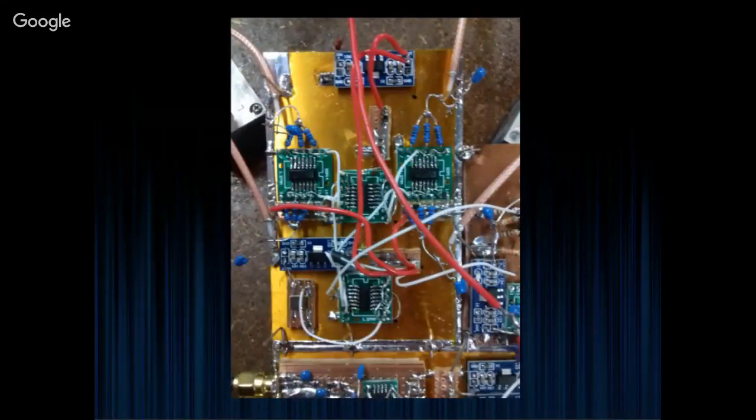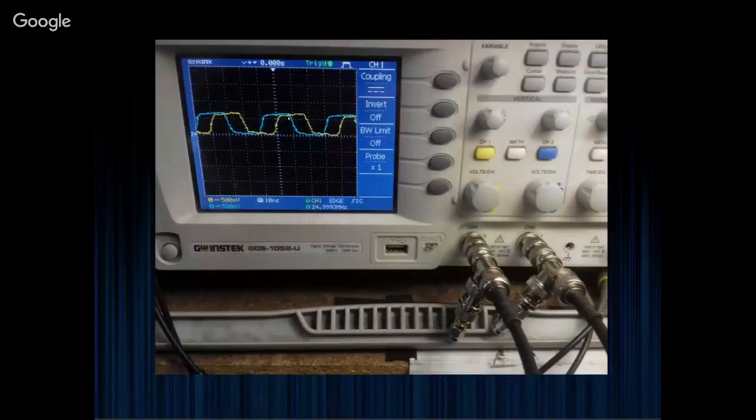There's a little oscillator down here, which is just a fixed frequency test oscillator. It's not really that important, it's not used at this point. And here are the signals in quadrature, so you can verify them. The other important thing to note is when you're reading signals on an oscilloscope, it's typically a high impedance load, so you need to terminate to ensure the signals are read correctly without ringing.